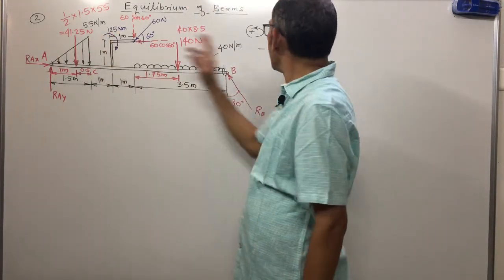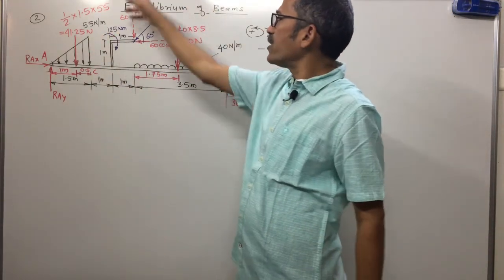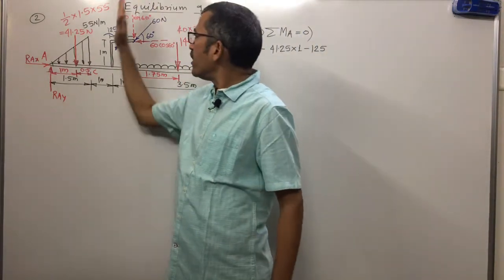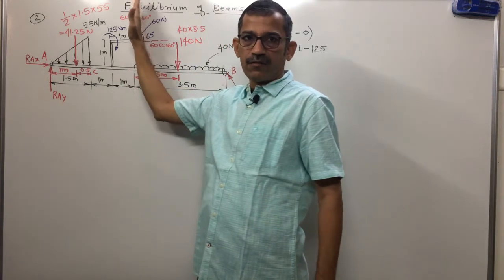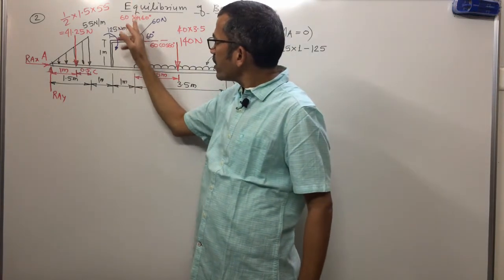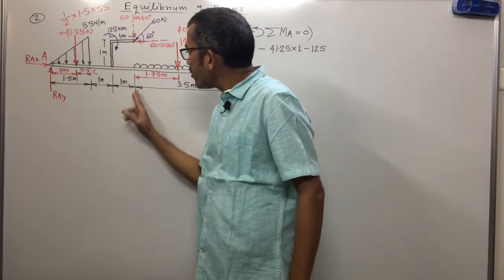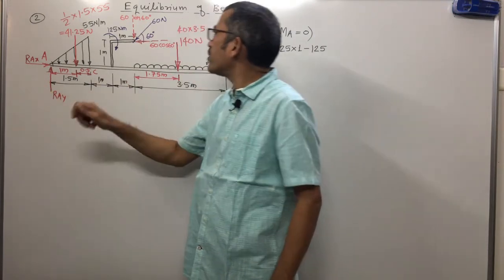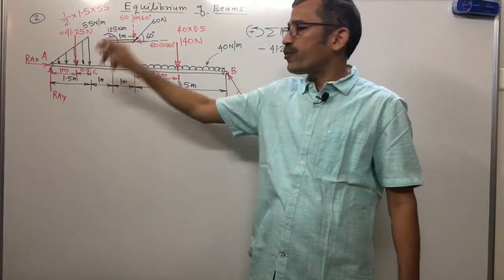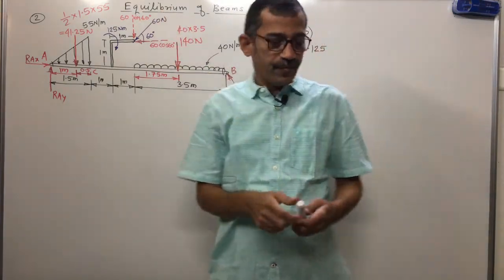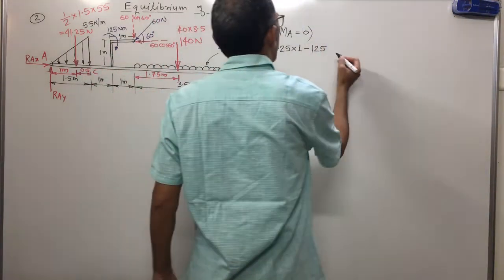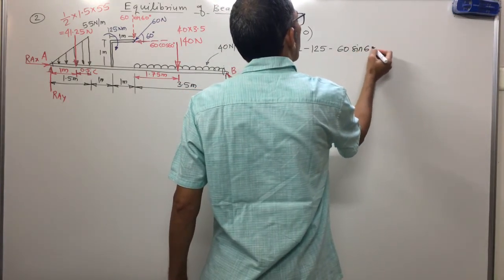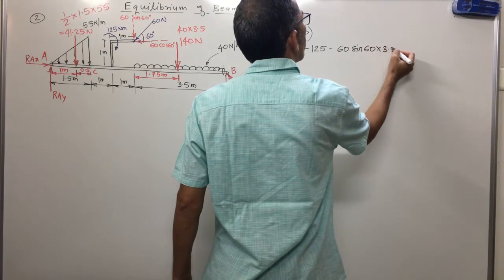Now 125 you have taken minus. So the vertical force: force vertical, perpendicular distance horizontal. Line of action of 60 sine 60 is vertical. If we measure the distance of this line of action of force from A, it is 1.5 plus 1 plus 1, how much? 3.5. Moment of vertical force about point A is clockwise. Minus 60 sine 60, distance 3.5.